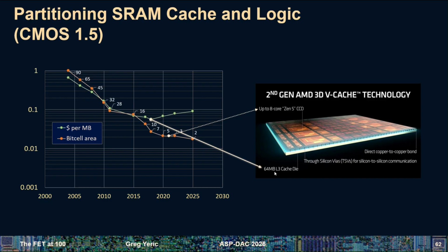And you're going to have some dummy, some unused columns of bits. And then when you test your memory out of the factory and you get a defect, like a piece of dust has fallen on this particular bit and that bit doesn't work, you have ways of terminating the use of the defective column and replacing it with one of your spare columns called redundancy.